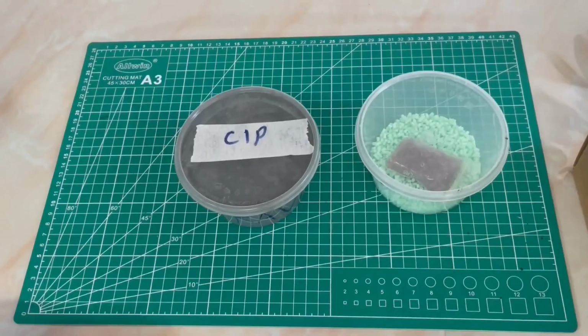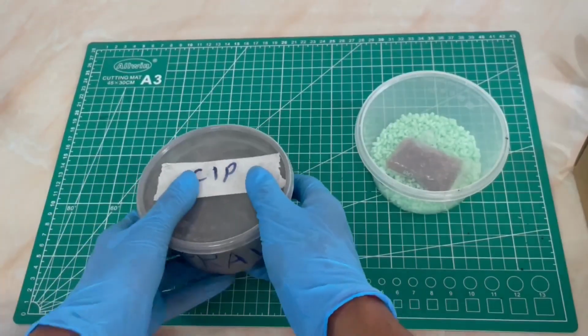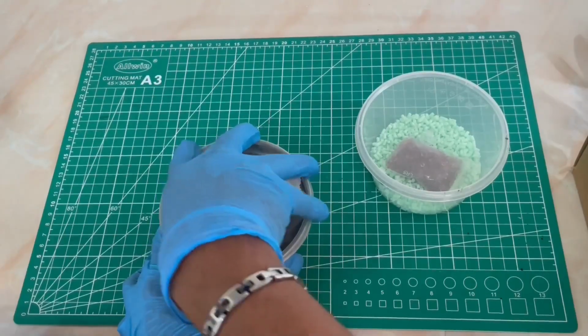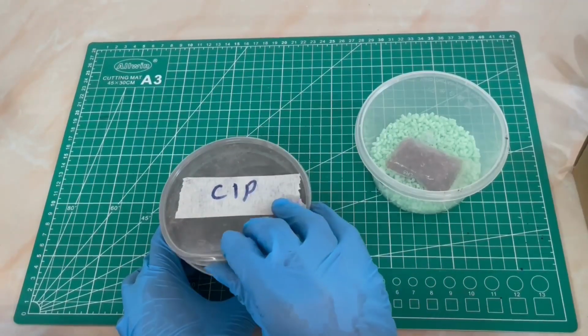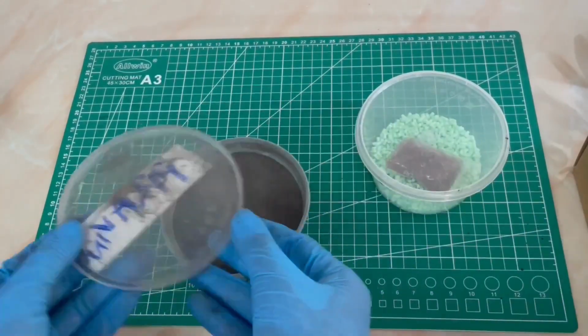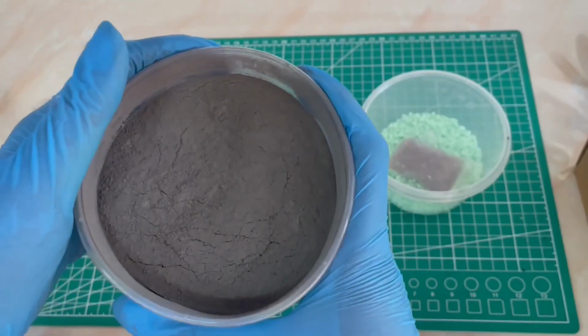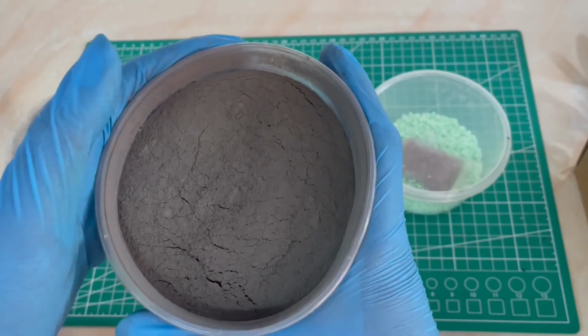To fabricate this MRE filament, we need two important materials, where the first one is iron powder. Iron powders are magnetically responsive, where it is physically attracted to magnets. The iron powder that I'm using will be carbonyl iron particles, known for its high purity. You can also use other iron powders which are commercially available.